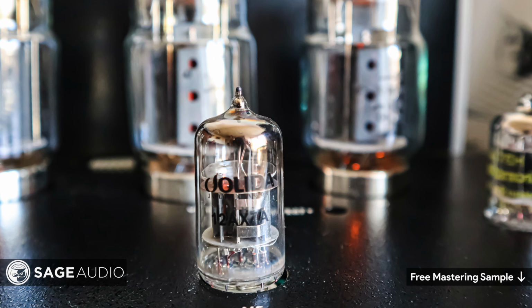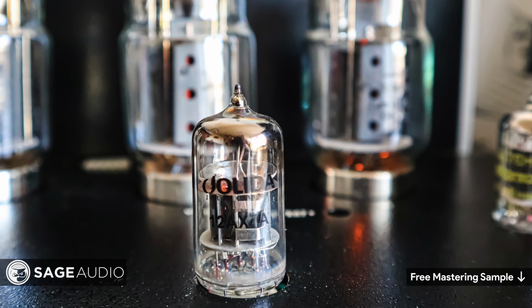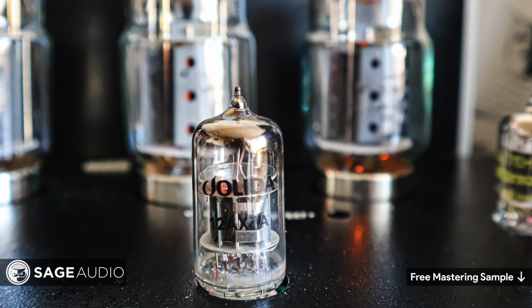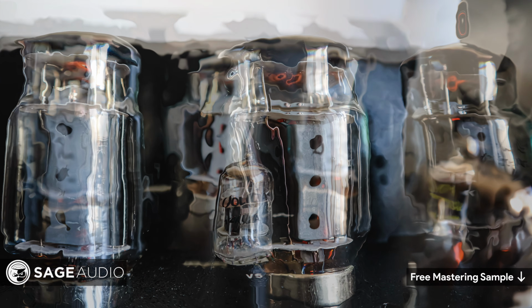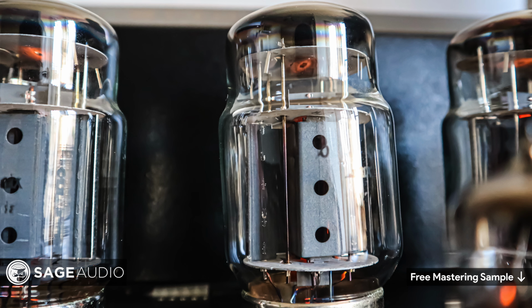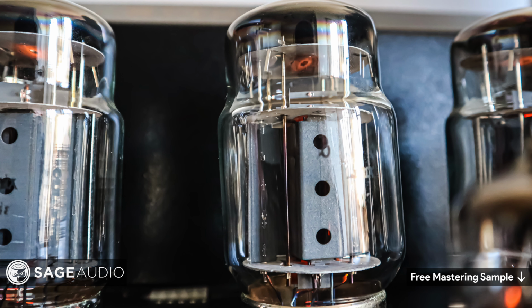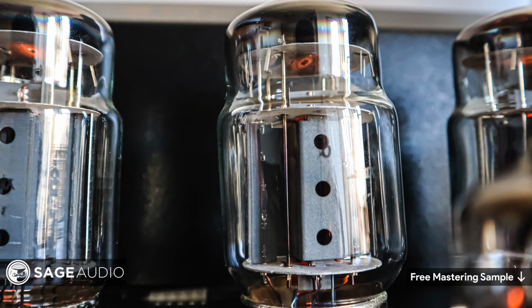Tube saturation occurs when the electrons can no longer flow from the tube's cathode to its anode due to a positive charge that's been created between the two. Now, this positive charge initiates once the incoming electrical signal is strong enough, in turn overwhelming the tube, so to speak, and no longer allowing for a linear input-to-output ratio.